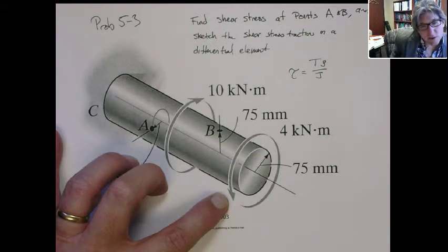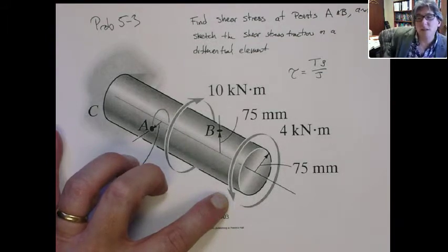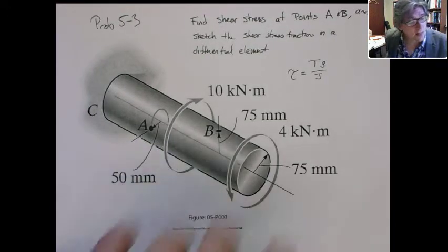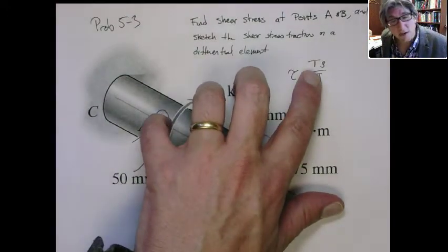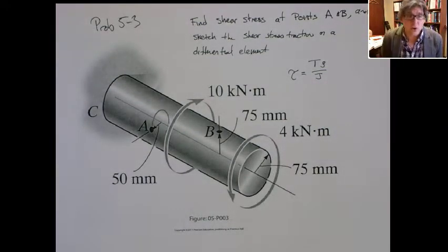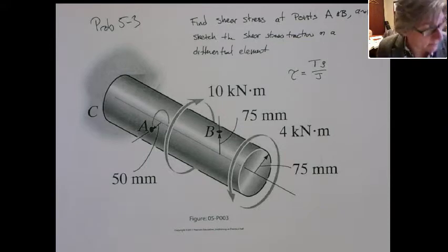As always, this is one of those things I see constantly. I've said it already about five times in class, and I still keep seeing it. Understand these equations: T is the internal reaction torque. Whenever you're determining stresses, it's always in terms of the internal reaction forces. For simple loadings, often those are equal to the external ones, but not always. Okay? Please don't make that mistake.